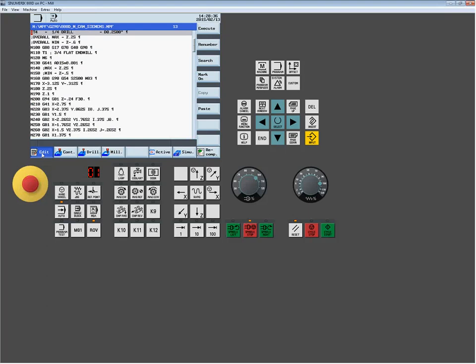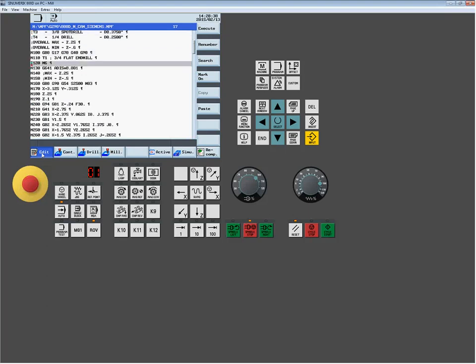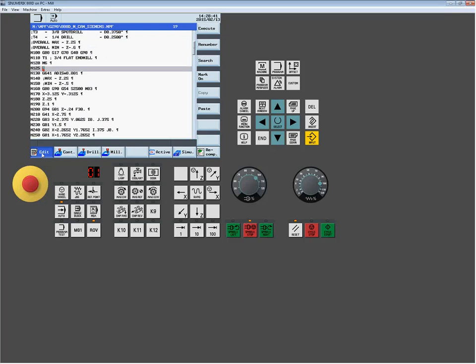So what I'm going to do is put it just below my tool change, and I can do a statement called TOFFR equals, and I'm going to put a negative whatever the radius value is. TOFFR sounds a funny kind of statement, but really what it is is tool offset radius. So we're adjusting the tool offset's radius.